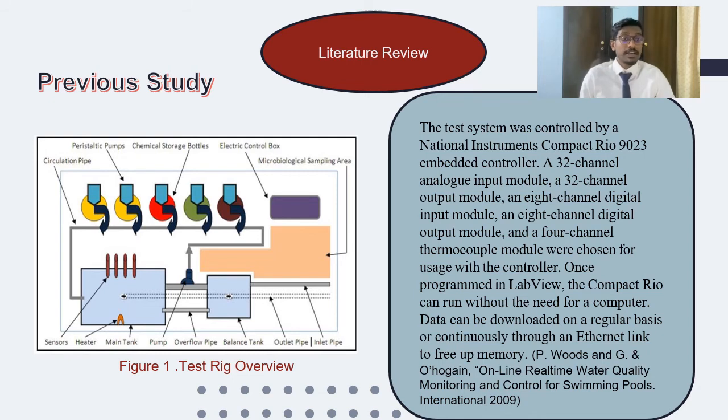A 32 channel analog input module and a 32 channel output module, 8 channel digital input and 8 channel digital output modules, and a 4 channel thermocouple module were chosen for use with the controller. Once the program is in LabVIEW, the CompactRIO can run without the need of a computer, and data can be downloaded on a regular basis or continuously through an Ethernet link to free up the memory.